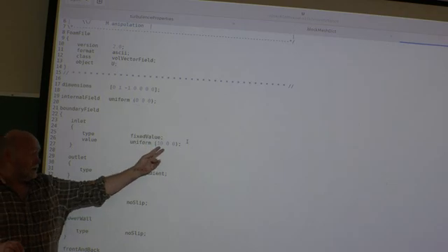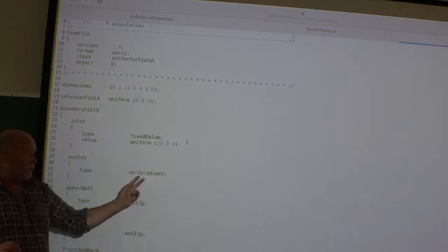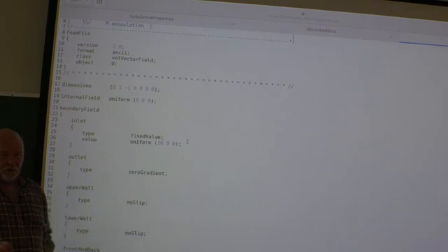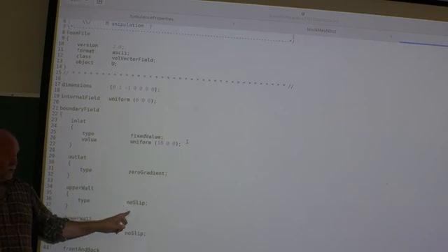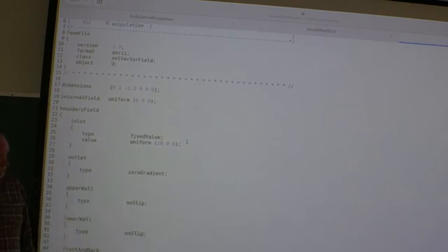Here you have a Dirichlet condition, you give a number. Here you have a Neumann condition, you give a derivative equal to 0. Upper wall, lower wall, just no slip. You could also here use the fixed value 0, 0, 0. That will be the same. And front and back is empty.